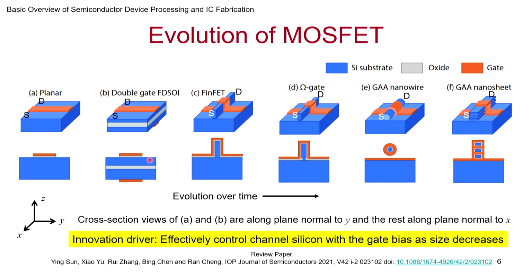The top film may be of the order of 100 nanometers or something, whereas the bottom can be of the order of a micron also. But all the same, electrically you have good connection. So this channel that is there at the top, you are controlling from the top as well as from the bottom. Okay, so this clearly gave better control of the channel compared to the planar structure, but that was not enough. So what do? Can you get other directions?